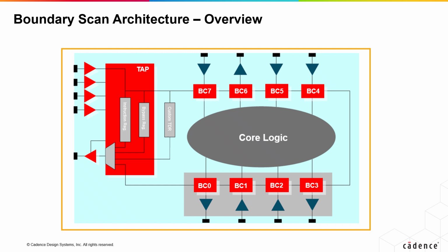The tool will build a default JTAG macro for the 4 mandatory instructions, that are bypass, xtest, preload, and sample. The JTAG macro can also be created based on user-defined instructions to control any number of custom test data registers for other special test structures like memory BIST or TAM logic, etc. If a custom test data register exists in the design, and you completely define the user-defined instructions before inserting the boundary scan logic, the boundary scan insertion engine will connect the JTAG macro pins and the custom test register pins.